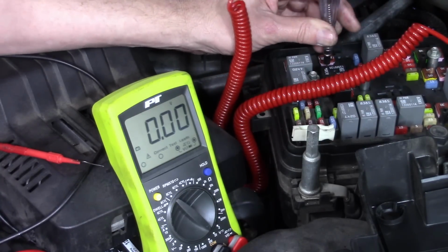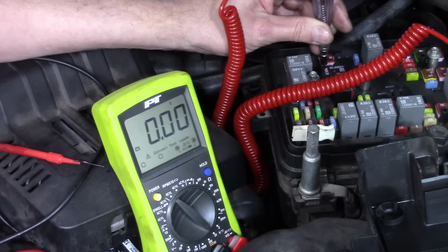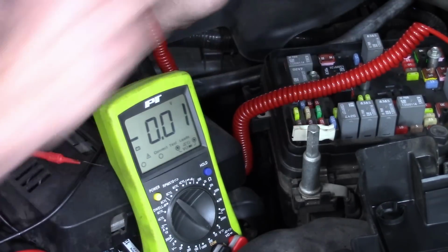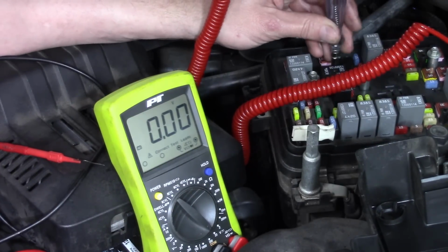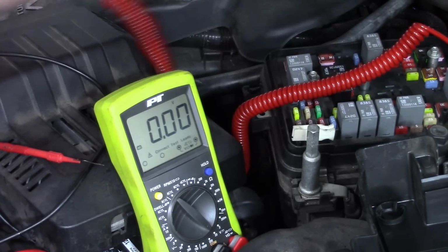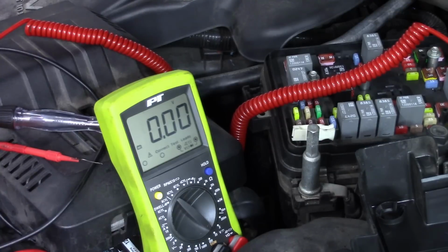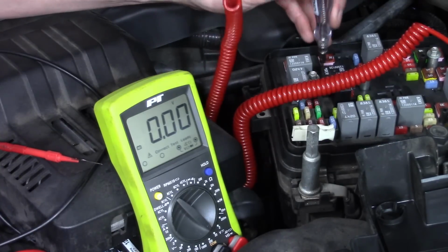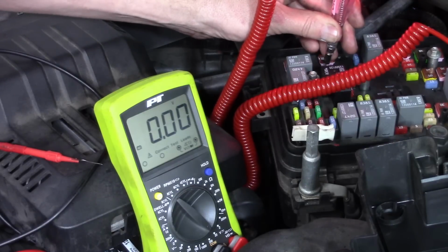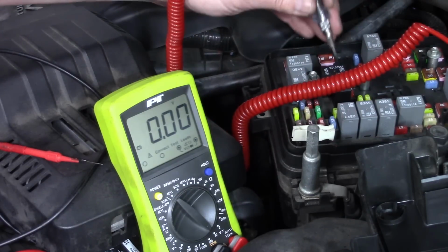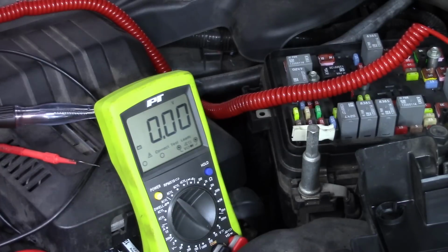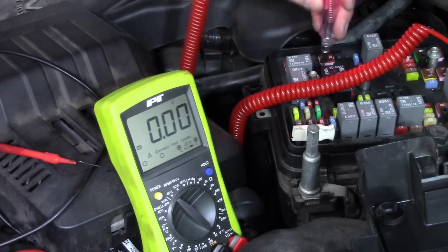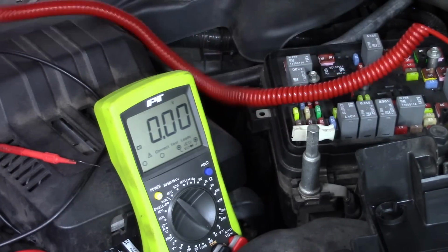All right, I know either that's going to be a load side or a control side power. Now what I'm going to do is test here and here on the other two relays. Neither lights up. I'm done right there. I know this is going to be a load side power on this particular vehicle. If one of the other relays lit up with my key off, well, then it's a little more challenging. Then you've got to do a little more research. This car, it's easy. That is a load side power.